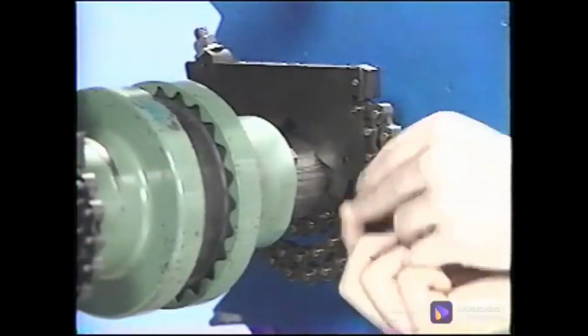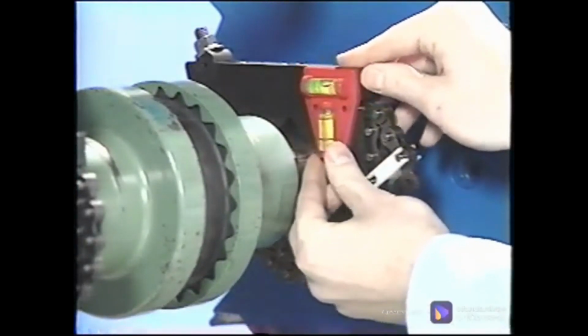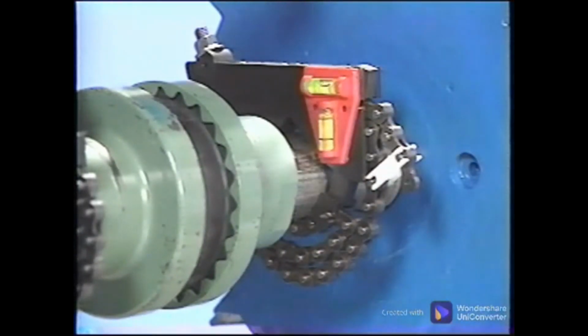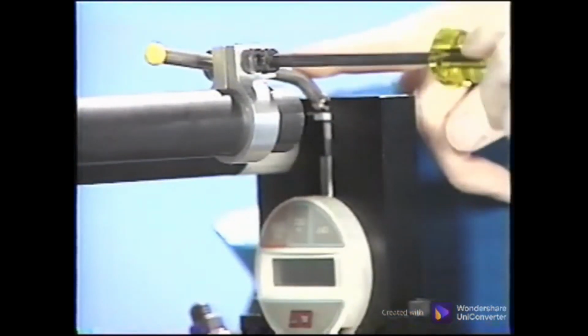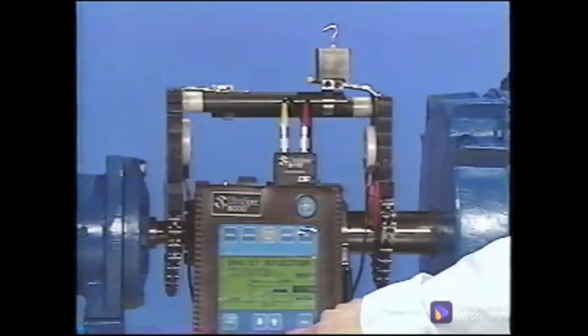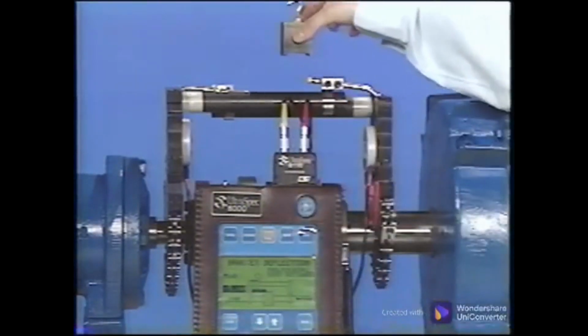Mount and level one bracket, then mount the other bracket, being sure to level it also. It is best that the brackets are in the same plane. Then mount the heads on the brackets, positioning the stems and bars to ride on the plunger of the opposite digital indicator. The benefits of an electromechanical system are more than just time saving.